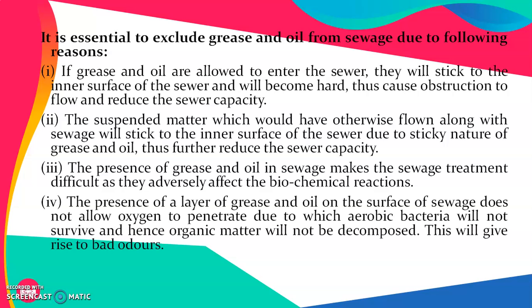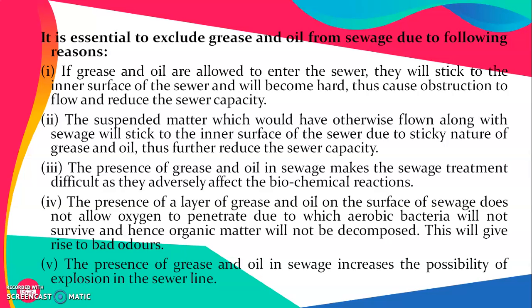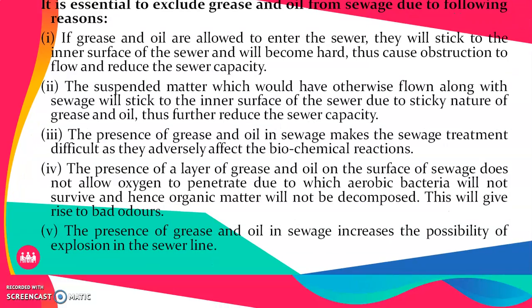A layer of grease and oil on the surface does not allow oxygen to penetrate, which again gives rise to bad odors and even interferes with the secondary treatment. Such presence even increases the possibility of explosion in the sewer lines.